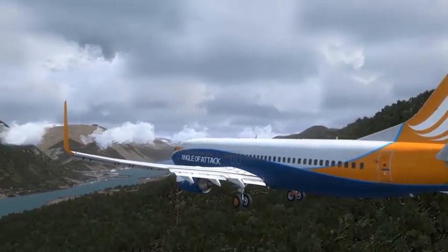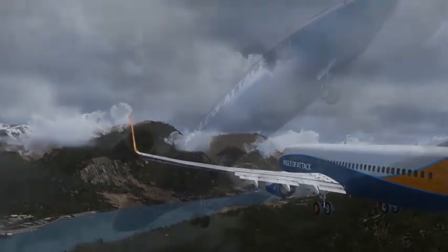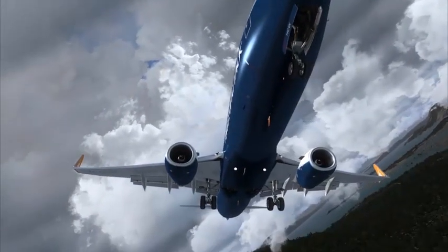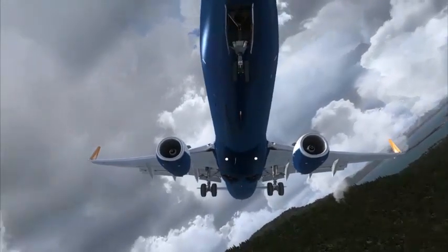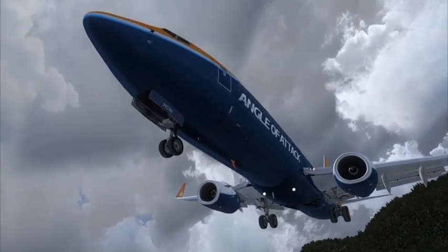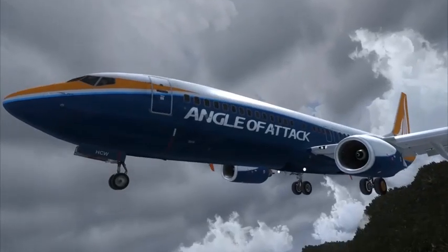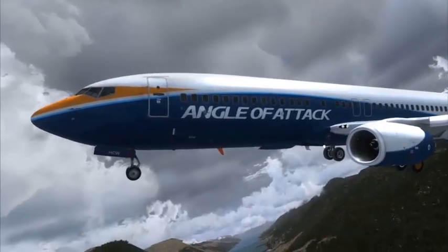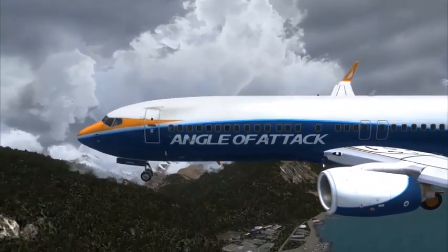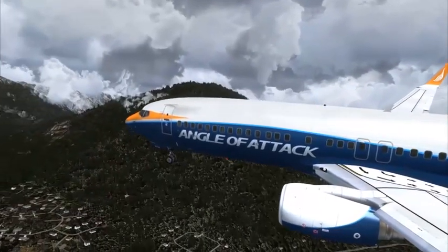Before takeoff, the pilots must also enter the landing field altitude in the landing field altitude selector, located below the flight altitude selector in the overhead panel. This is done so that during descent, the pressurization system pressurizes the cabin to 0.15 psi below the landing field altitude selection in order to avoid a pressure bump from discomforting passengers during landing, similar to how it's done during the takeoff phase. In this phase, the cabin altitude rate of change is in the order of 500 to 750 feet per minute, depending on the aircraft model.